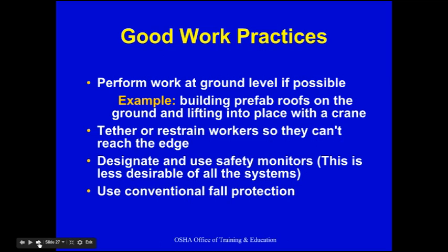Good work practices. Make sure that you perform your work at the ground level if possible. Do as much of your stuff on the ground. Build your chimneys or your soffits or whatever you're putting up. Build them all on the ground and then bring them up and install them. It's much safer to do it that way.